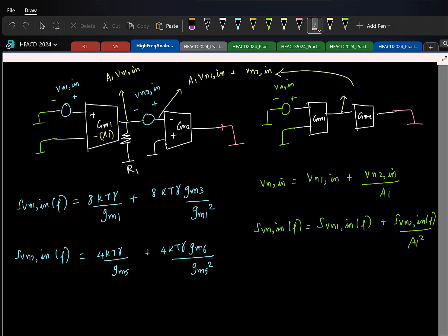But otherwise, if it's coming from the output resistance of transistors, that doesn't add any noise. Cool. So now this is the deal. In a multi-stage OTA, maximum gain is coming from which stage? Yeah, the first few stages. In a 2-stage, this guy will have the maximum gain.